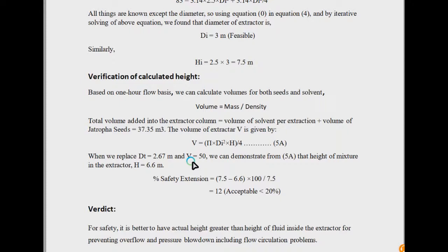Like I have an oil flow required of 29171 kilogram per hour. The time has been multiplied, and you calculate the mass based on the equilibrium contact, and from that mass you can convert to volume using the density.